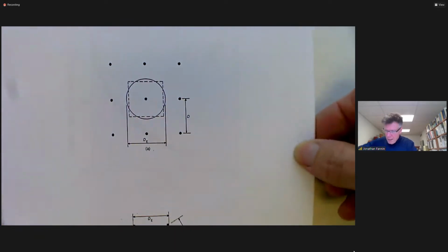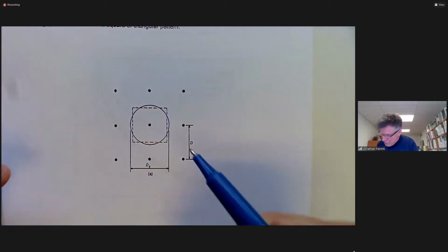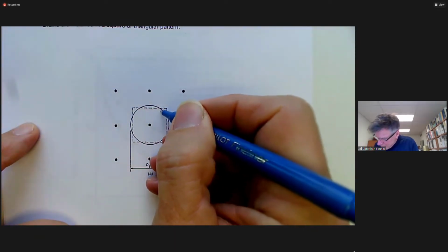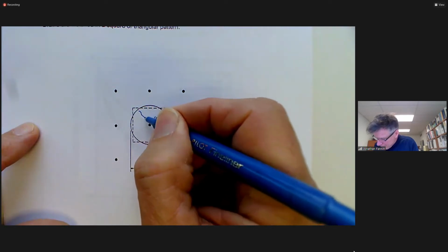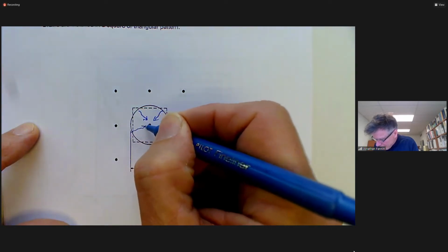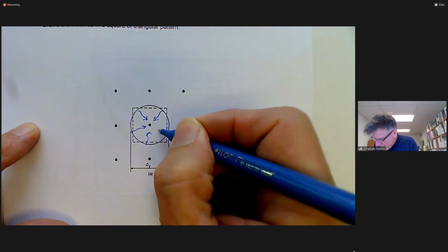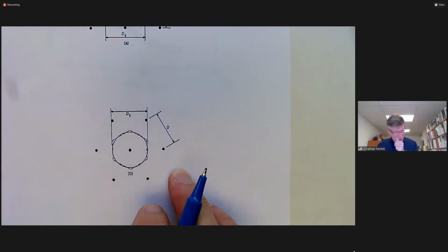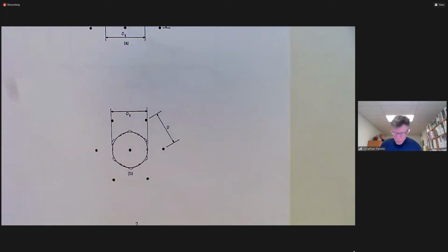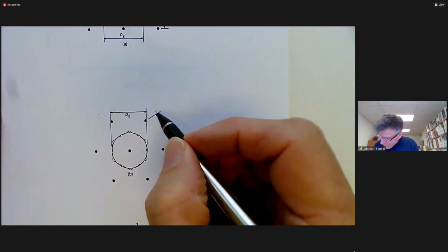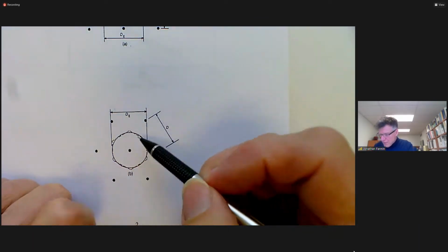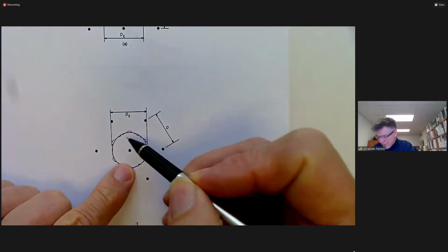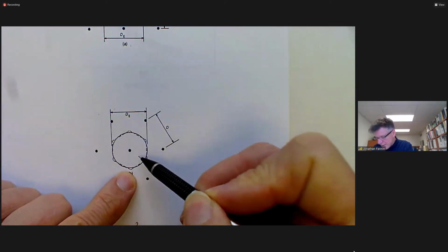Okay, and the drainage is going to be radially towards the wick drain. Radial drainage towards the wick drain. So if we have a drain spacing, then we can correlate the diameter of the equivalent cylinder of soil that's being drained.